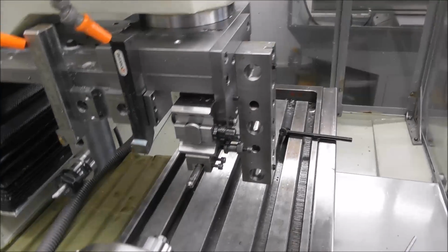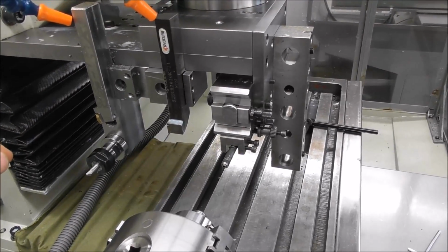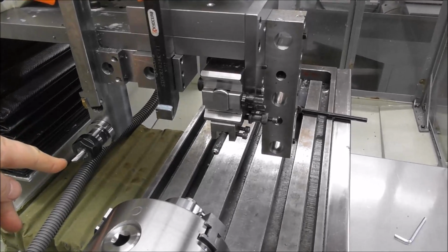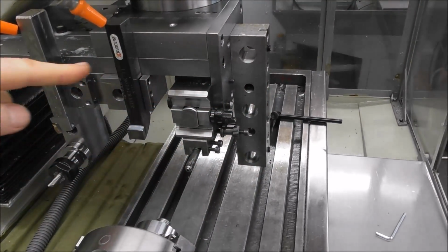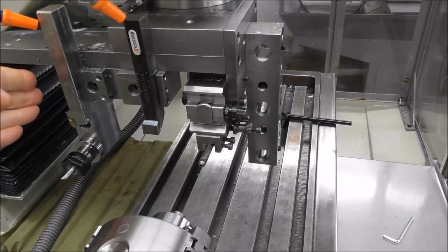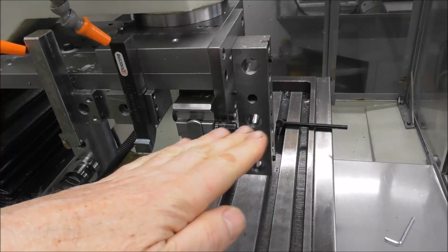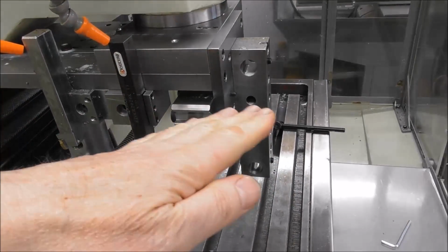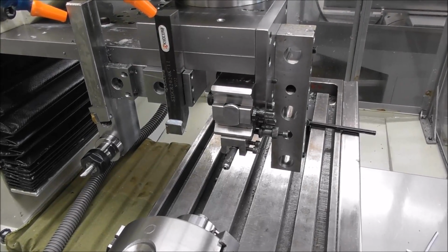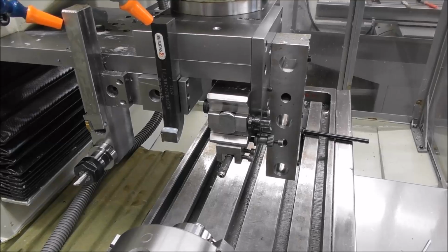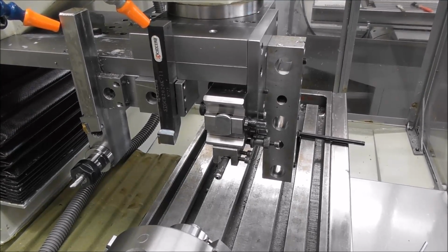The advantage of this type of gang tooling platform is that you've got a lot more area to mount tools. If you think of it as an inverted U shape, so that you can still use the tailstock in the middle, you can have the TTS type holders on either side of the inverted U and other ordinary type tools on the horizontal portion. You've got much more capacity for holding tools than you have on a conventional CNC lathe that just has one axis of movement, the X axis.